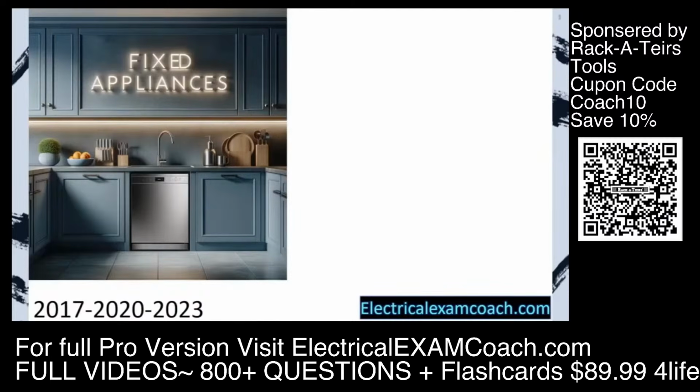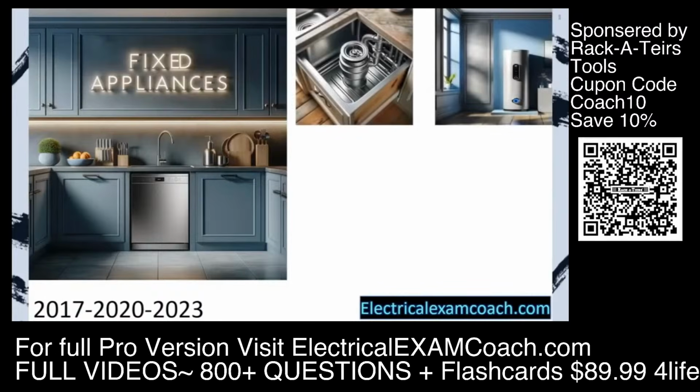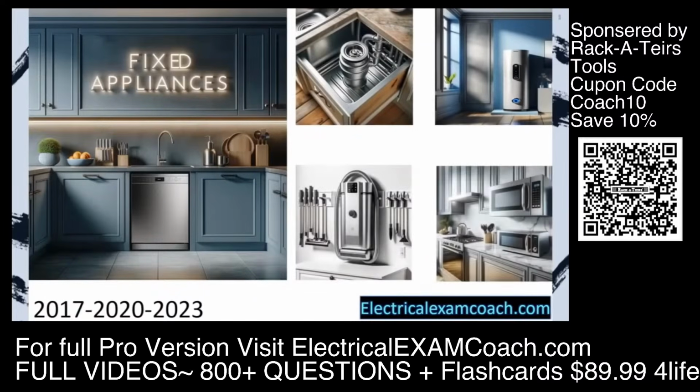Today we're going to be learning about fixed appliances and how they work into a whole house load calculation. Fixed appliances include things like dishwashers in this picture, but it also includes garbage disposals, water heaters, central vacuum systems, microwaves, and pretty much any other appliance once it's fixed. You'll notice in this bottom right-hand picture that there are 2 microwaves. One is not fixed, and the other one is fixed. When you fix it to the wall or fix it so it can't move, either with plumbing or mechanical vents or anything else, it now becomes a fixed appliance, and there's a special way that they calculate them when doing a whole home load calculation.